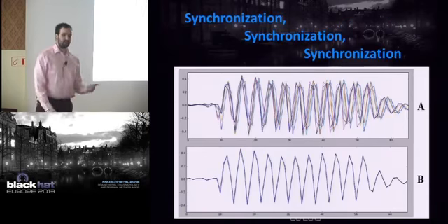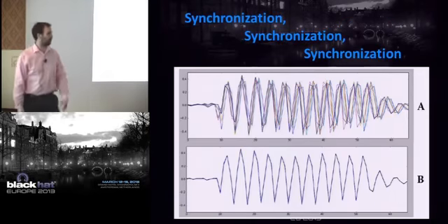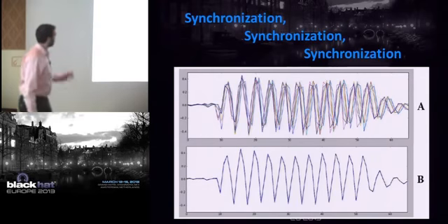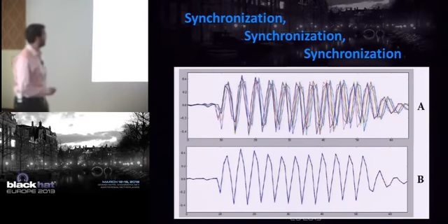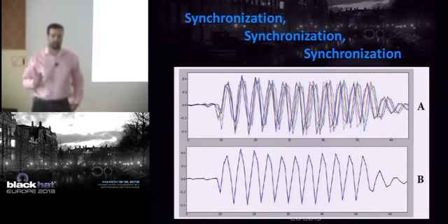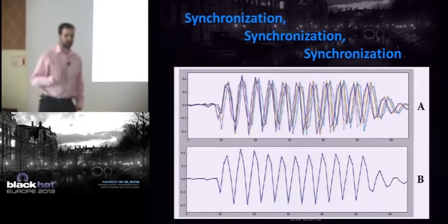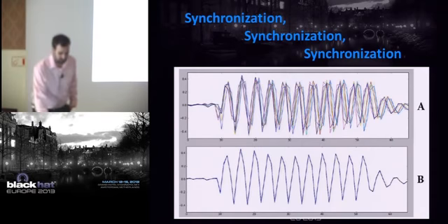And where this comes from, the core part of this, is this requirement to synchronize your power traces. So these two graphs, the top one is sampling at 100 megasamples per second. This is sampling a hardware AES system that basically doesn't work below about 250 megasamples per second. You need the minimum speed of the scope.